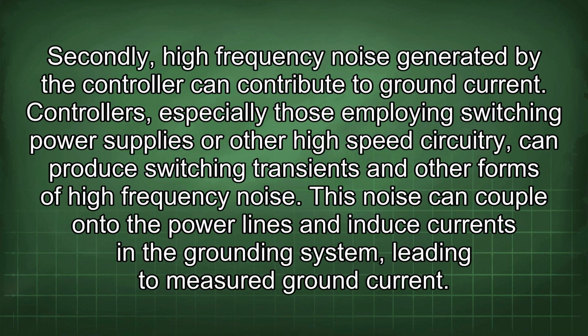Secondly, high-frequency noise generated by the controller can contribute to ground current. Controllers, especially those employing switching power supplies or other high-speed circuitry, can produce switching transients and other forms of high-frequency noise. This noise can couple onto the power lines and induce currents in the grounding system, leading to measured ground current.